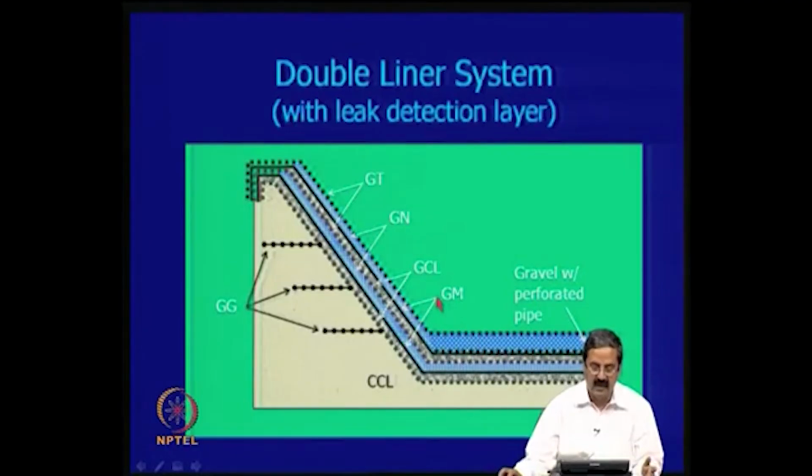I will show you later that some specifications demand that you need to have double liner systems, like a geomembrane here as well as here, because if there is a water table very close to this, then you can't contaminate it, right. So, for example, leachate collection comes here, the leachate water should be collected in some sense, then it should be pumped up. There are so many operations, and I will show you a detailed presentation of actual landfills in many places.